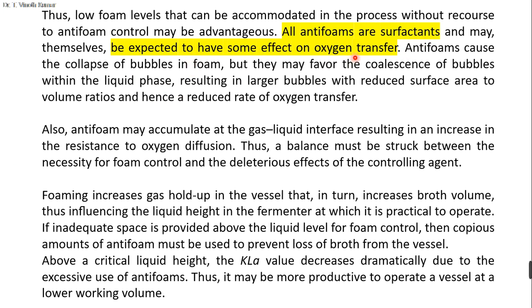Surely, 100%, it will affect oxygen transfer, but we have to be very careful. The effect should be negligible, because the antifoam should not interfere with oxygen mass transfer. So we have to take that into consideration and select a particular type of antifoaming agent for the particular fermentation process.